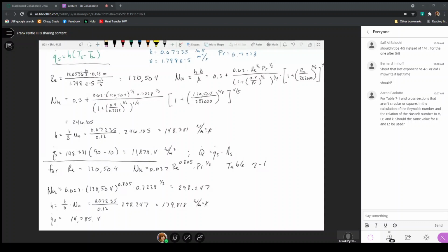as the heat flux. So with these different values being calculated, it's important that the work shown in making that calculation indicates exactly what correlation is being used to write the expression for the Nusselt number, because from that Nusselt number is where we get the heat transfer coefficient necessary to calculate a heat flux for this problem.